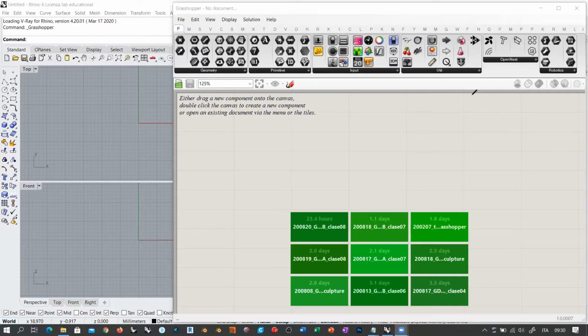Probably, as I was saying to Sagar, you already know something about mesh modeling, but I want to go through a very quick introduction. You know that mesh objects are a set of vertices connected by edges, and when you have a closed loop of edges, you define a polygon, or the so-called face. When you have a mesh object, you can have several types of situation. The easiest one is having three vertices and then having some triangular face. Then there are the quad faces with four vertices, of course.